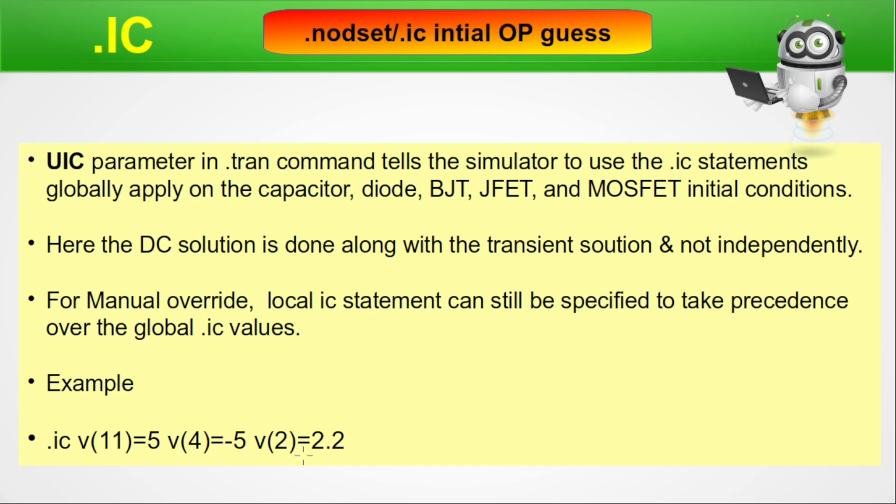Once you consult the log file, you will come to know what went wrong, and accordingly what we can change in the .IC or the .NODESET. It is not expected that as a beginner you become proficient in using .IC or .NODESET, but over time, or in case you have some experienced person in your company, you can take the help of that person, or you can take the help of the application engineer by filing a ticket in the support website, by telling the situation or giving the log file, right? And this way you will have a working experience.